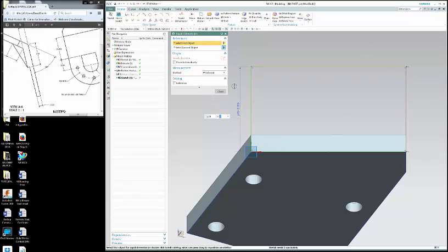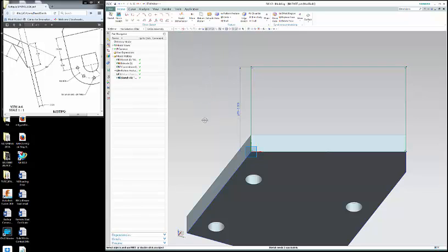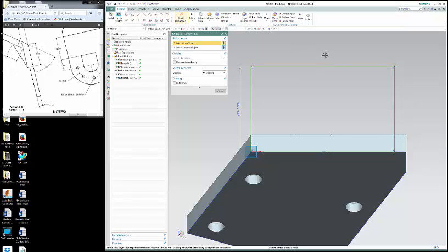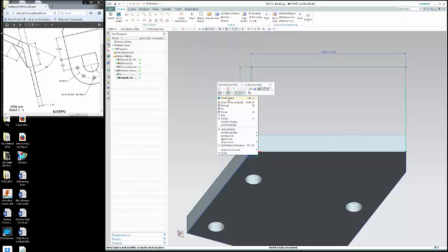And everything else should be okay, I do believe. Let's see. Sketch needs one constraint, so we've got to see what's going on here. Let's see, is it going to move off there? Oh, nope, it's still moving here. So we could go in there and do several different things. We could put some kind of a constraint on there, but I think I'll just do a dimension. Let's do a dimension here. Make that 3.5. And we'll just right click and finish.